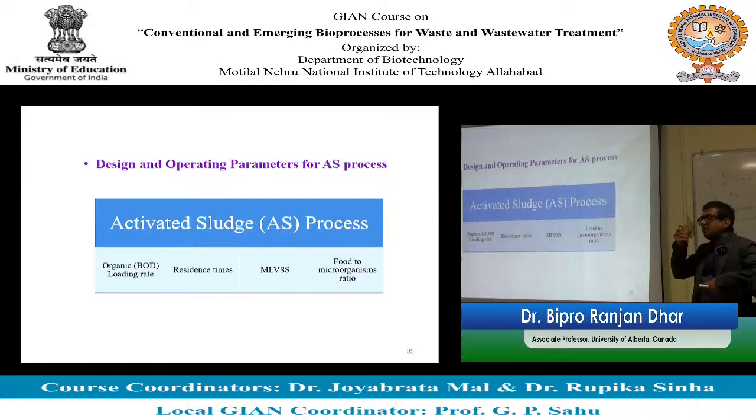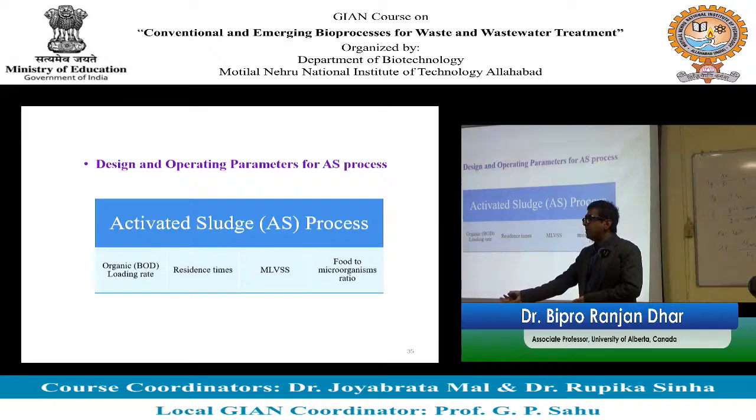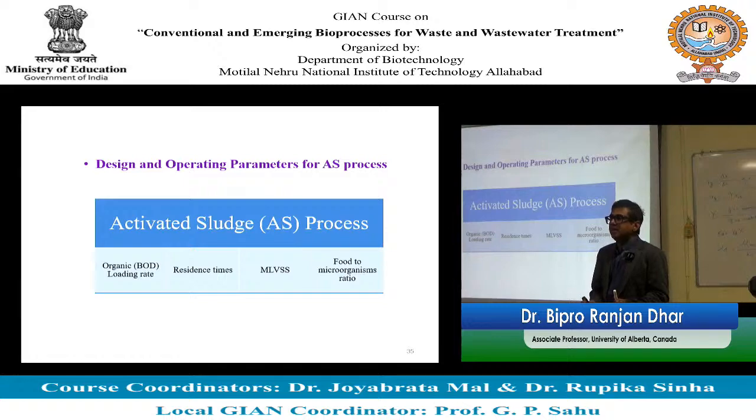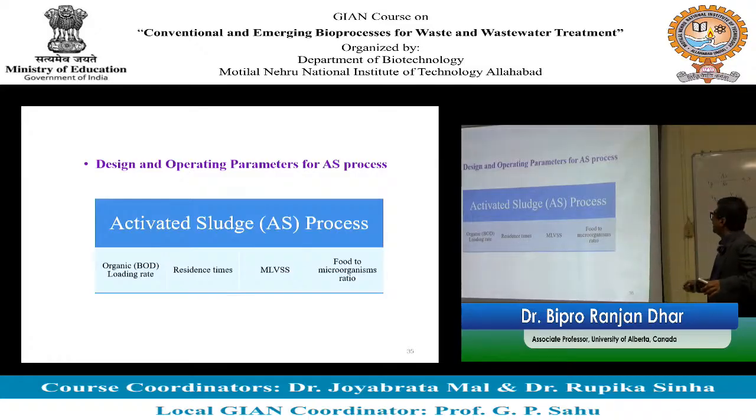MLVSS is another term, called mixed liquor volatile suspended solids. What is mixed liquor volatile suspended solids? Is MLVSS related to substrate, right? No, MLVSS is related to biomass. We want to keep a certain concentration of biomass in the reactor, because we want to make sure that we have enough biomass concentration to achieve our goal. So what is our goal? We want to achieve, let's say, 25 milligram per liter BOD, just as an example. So mixed liquor volatile suspended solids is used to measure the biomass concentration in the reactor.